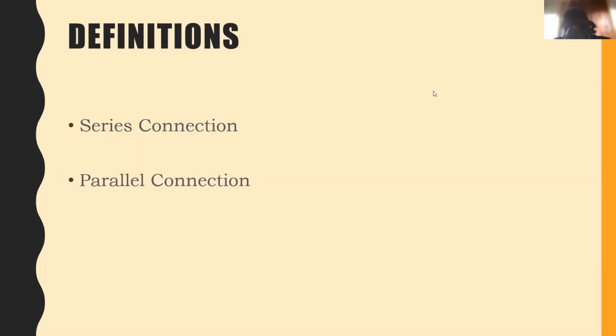All right, so it is that the current entering the node, connecting the two elements, divides between them. Now we have that clear. In terms of series connection, the current leaving one is the same current entering the other. Can be equal, but not necessarily the same. And then we have the definition for parallel. Now we're going to use those definitions when we look at two-port networks. We're going to stick scrupulously to those definitions.